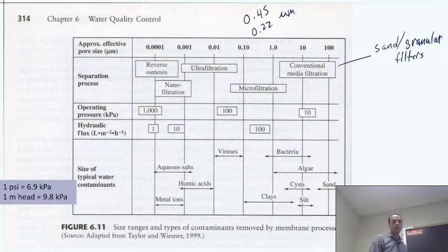And actually I'm going to take a step back from there. Again, looking at the microfiltration and the conventional, the pressure requirement in kilopascals is really somewhere between 10 and at the most 100 for there. And just as a reminder or a demonstration, the pressure units here, so kilopascals, about 7 kilopascals is 1 psi.